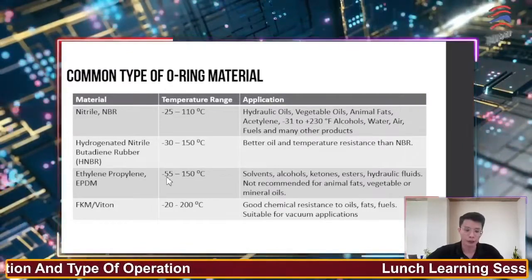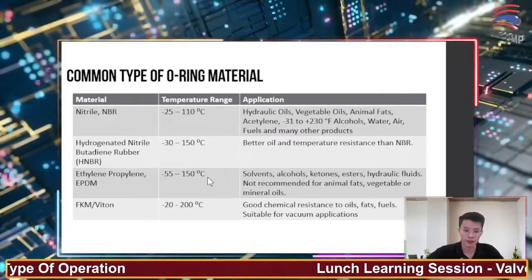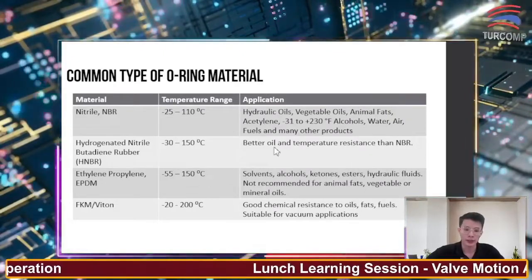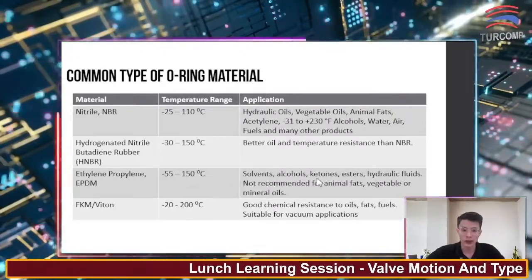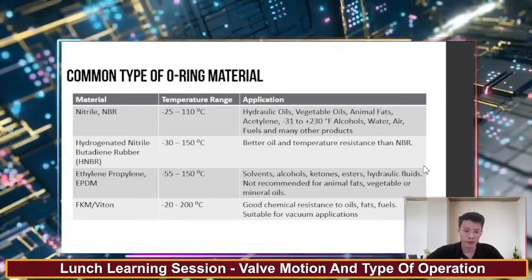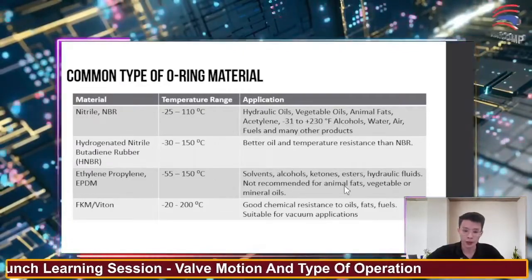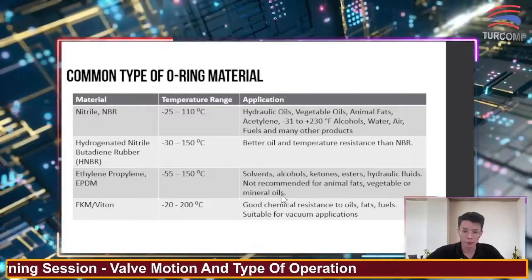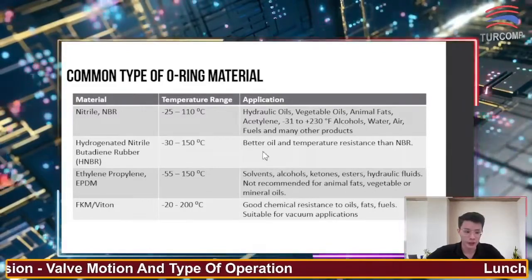The temperature range is from -55 to 150 degrees Celsius. The suitable applications are solvent, alcohol, ketone, ester, and hydraulic fluid. For EPDM, it is not recommended for animal fats, vegetable oils, or mineral oils.